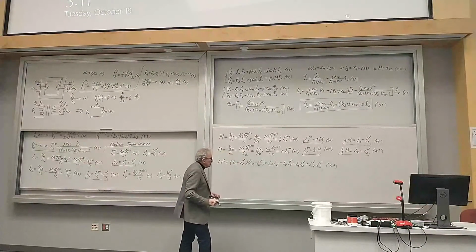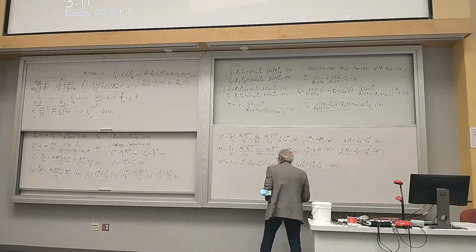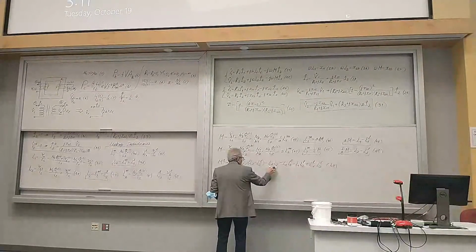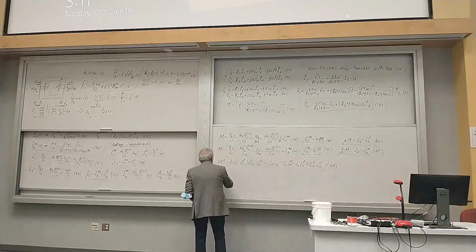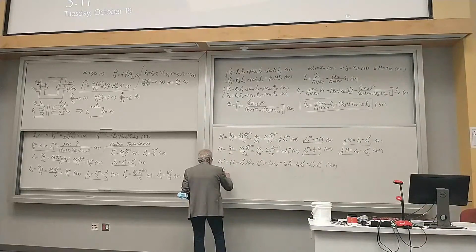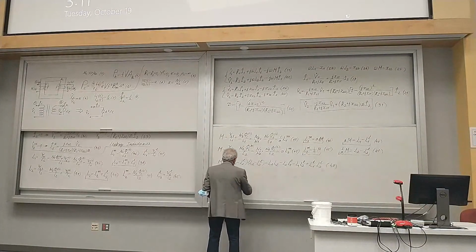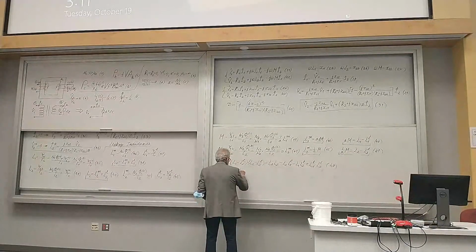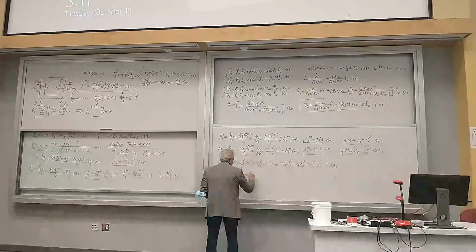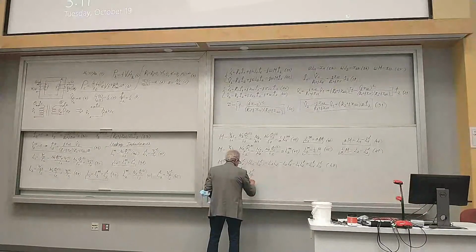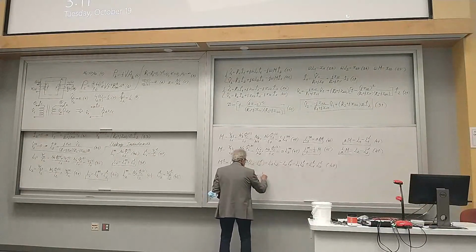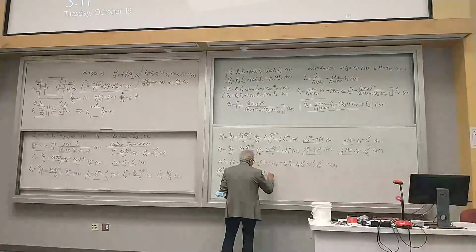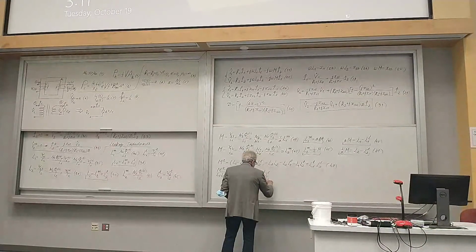And now the leakage inductance is very small. But before that, what I will do next is divide this expression on both sides by L sub 1 times L sub 2. Then it will be 1 minus the primary leakage inductance to the primary inductance, minus the secondary leakage inductance to the secondary inductance, plus the product of leakage inductances divided by L sub 1 and L sub 2.